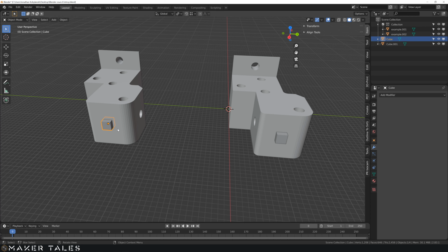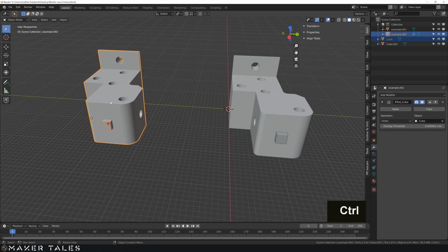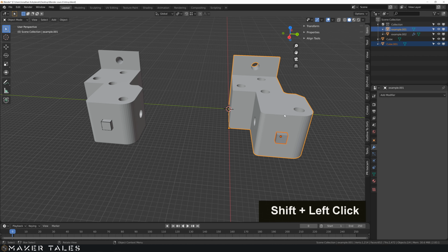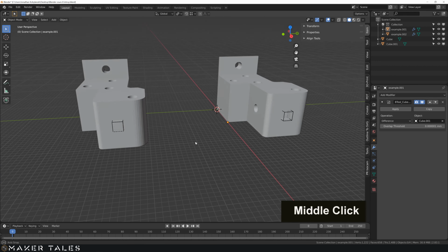So we know that these will edit together. You can actually now assign this to be a Boolean add. So Ctrl numpad plus, and we're going to make you a minus, Ctrl minus. So you can already see we have a joint here. Now this could be anything from washers to screws to whatever else you have going around your object that you want linked.